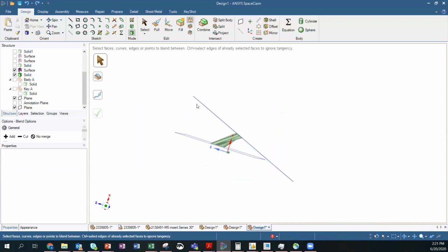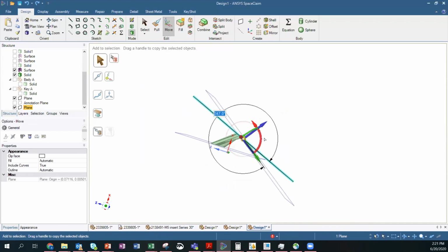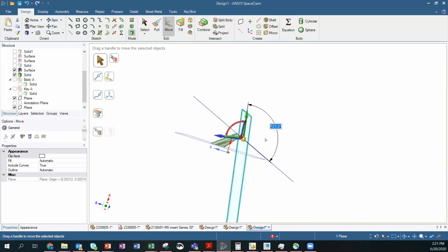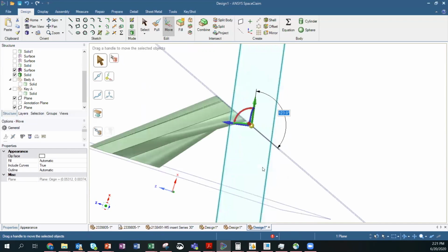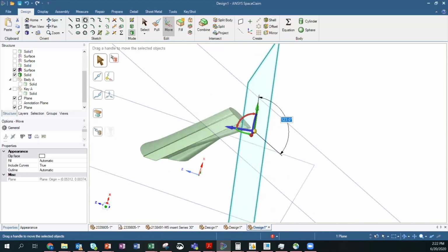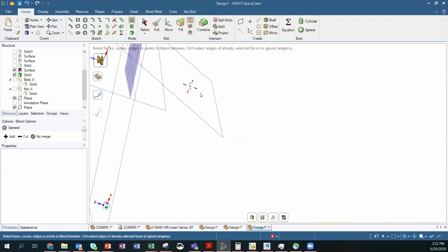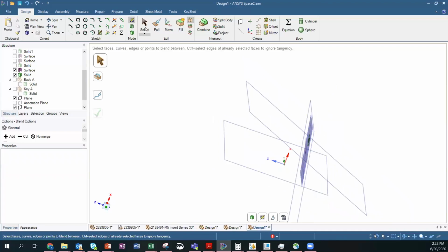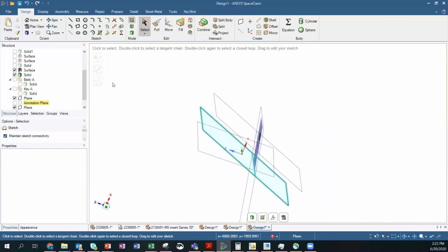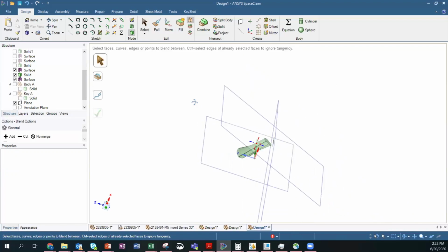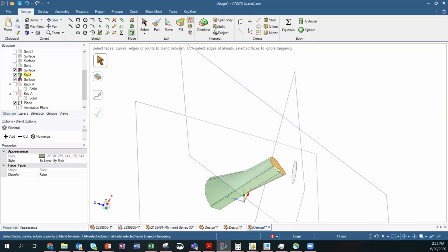If you want, you can specifically design, for example some designs we do a valley at 123 degrees. So now you create another surface from here and you can blend it. You can just keep on doing it all day. So blend, select the surfaces and everything. Let's select these two surfaces.